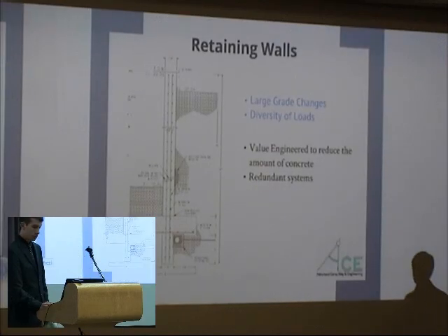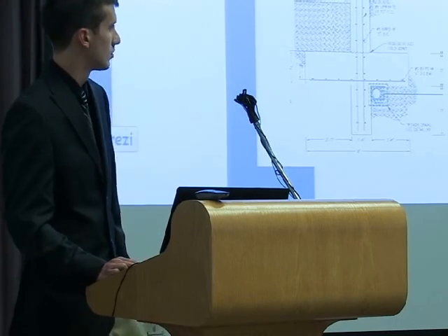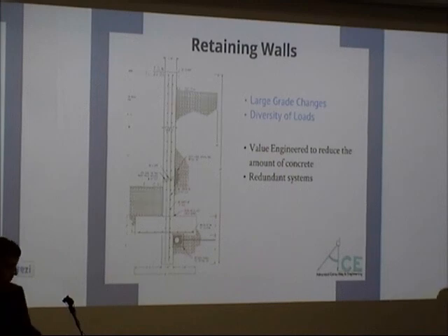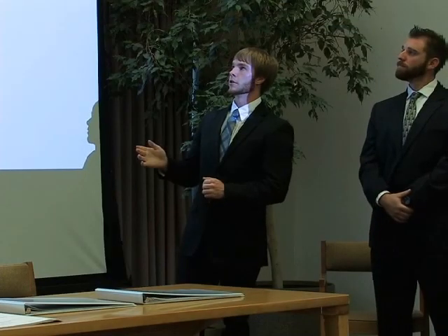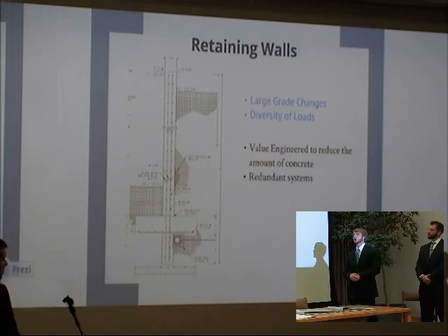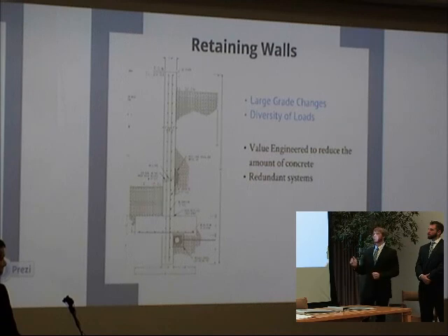Thank you. Again, I'm Dan Litton, and I designed the retaining walls of this site. This is a rendering of the retaining wall behind our retail buildings against the seaside. So in order to design this, I picked a worst case scenario through iterative designs, and I filled the back of the retaining wall full of water as if the drainage was full. This created a need for that shear key at the bottom, which is 3 feet deep. Seems very large, but if you look at the volume of concrete compared to what we would need for high enough factor of safety against sliding, it ends up being conservative in our volume of concrete.